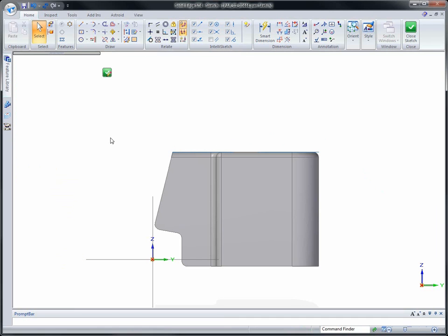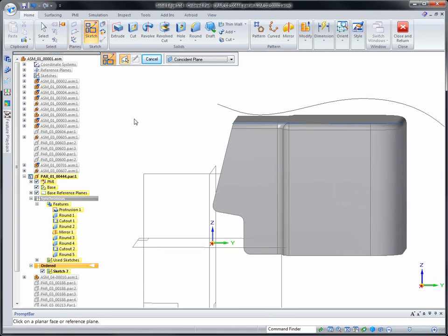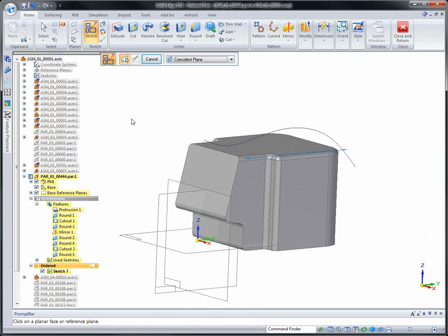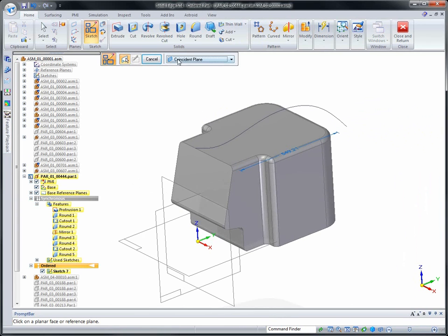Just clicking points in space, we can create a B-spline curve. Next, we need to create the cross curve. We're going to do this with an arc at a parallel plane along the y-axis of the engine cover.